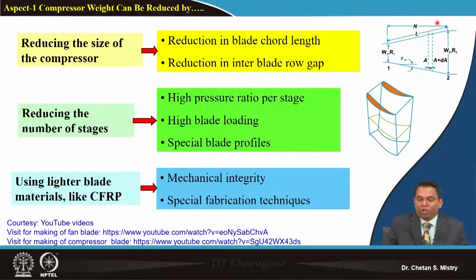And if you recall, we discussed that the blade passage for the compressor or the fan comprises a number of such diffusers. So at the hub, mid station, and near the tip region, we have different shapes of the blade, or interblade diffusing passage.